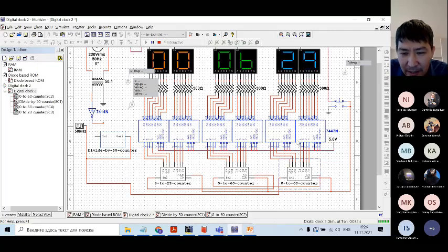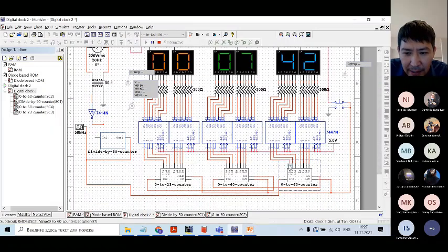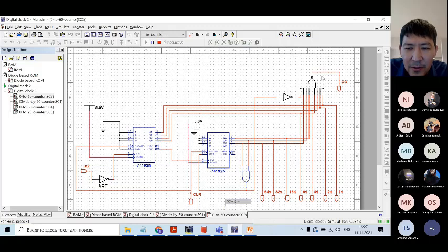will go to the decoder. So these two decoders are just 7-segment decoders. So it will just decode the BCD. They will decode just to the 7-segment code. Okay, but here, if you will pay attention, I added some NOR gate. So I'm using this NOR gate because when it will count from 0 to 59, then it will update to 0, 0. I need some other clock that will have frequency less than 1 Hertz, so it will be frequency 1 over 60.